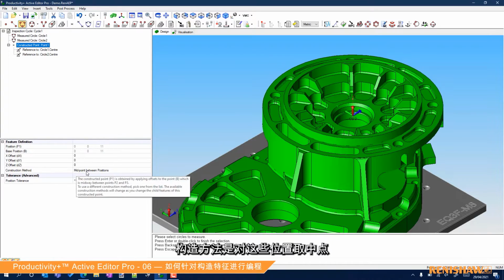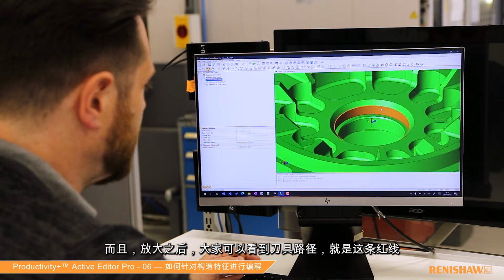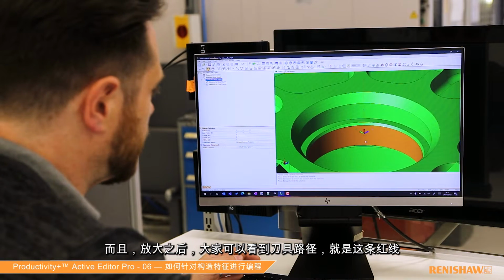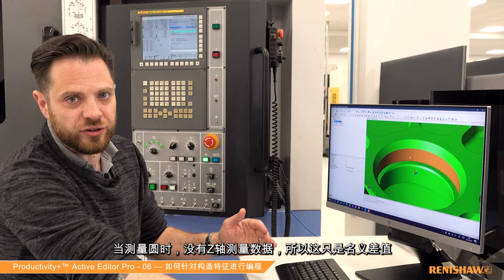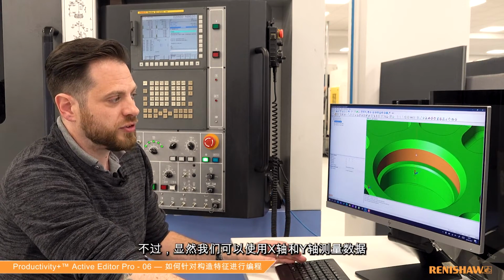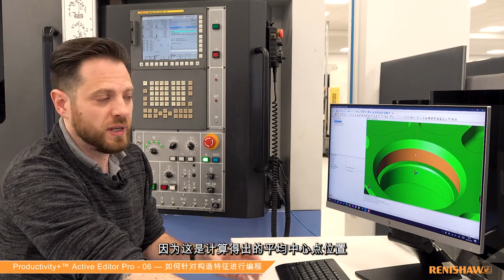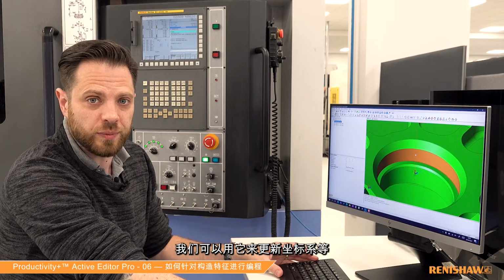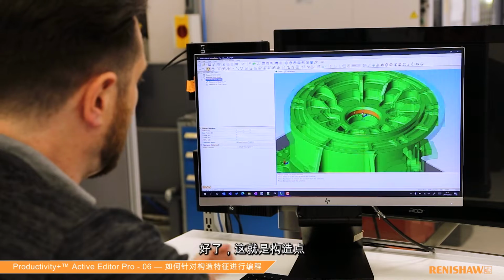The construction method is the midpoint between these positions. And actually, if I zoom in, what you will see now is a toolpath there, so we can see this red line. So the top and bottom red dots are the centers of our two measured circles, so this blue one's at the midpoint. Now, there is no metrology information for Z when you're measuring a circle, so this is just the nominal difference. But obviously, the X and Y, we could use that, because that's a calculated average center point, and we could use that to maybe update a coordinate system, for example. Okay, so that's our constructed point.